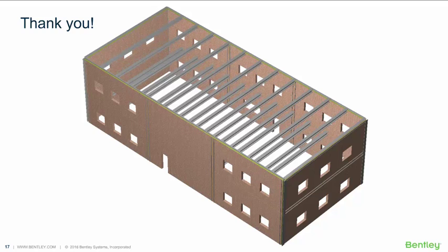But depending on how it's set up, whether there's any gravity framing sitting on the infill itself, it could be that the configuration of the model is such that you can get it to take only lateral load and no gravity. So strictly speaking, the answer is no, you can't do that, but it could be possible with the way that you choose to model it.